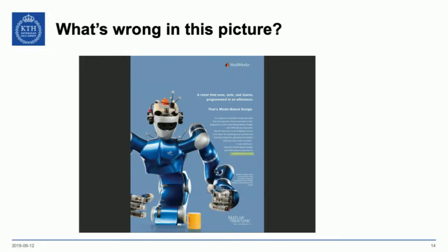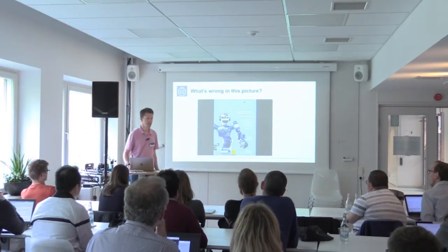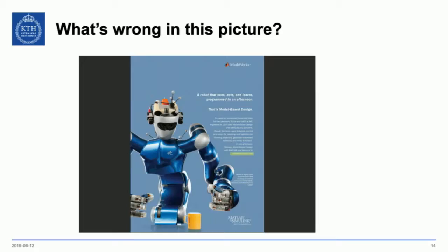They're cheating. What are these things? There are small IR reflectors. That means that they probably have a motion capture system rigged up in the room. So they use an external positioning system to find where this thing is, because it is really hard to solve the localization problem. So they solve it by installing infrastructure.